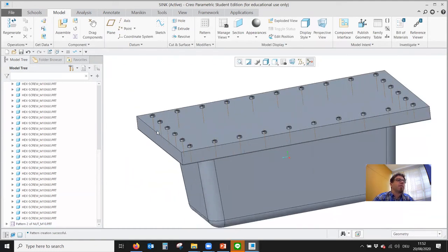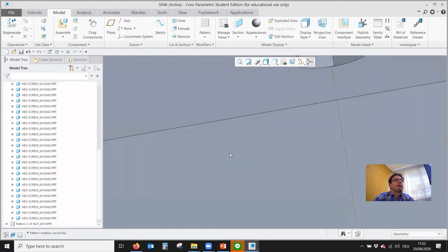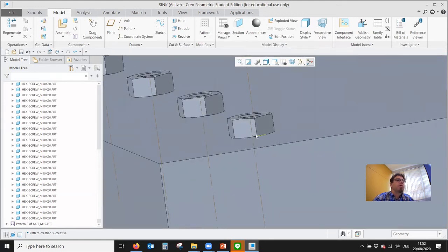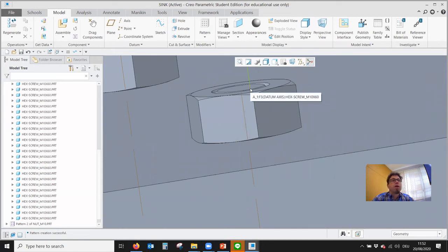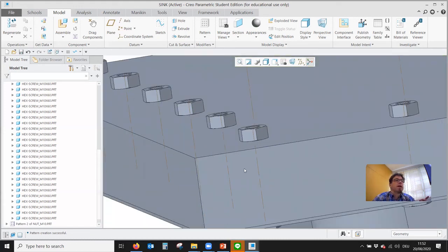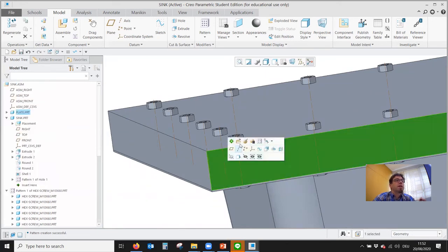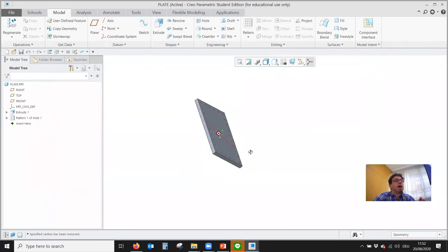Now the great thing is, because I placed the nut separately, and I also said before that technically, people would say this screw is a bit too short. Design rule for screws and bolts, you should always make sure you make full use of the complete thread, and that is only the case if the screw is actually coming out of the nut a bit, because you have tolerances, right? Some of the screws might be a bit shorter, and then the other parts might in reality be a bit thicker. So what I will do now is, this is new, I didn't show that before, I will now open this plate and make it a little bit thinner.